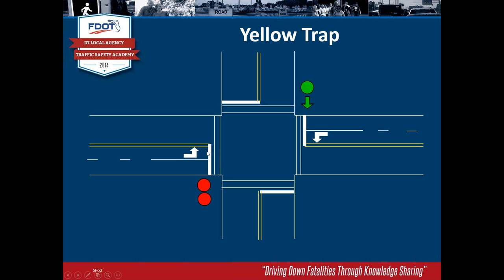Well, it's because he thought, as it went from circular green to circular yellow to circular red, that he could just go, that's the end of the phase, let me go through here. But this guy saw green while he was having a circular green. He saw green while the guy was in yellow and saw green while the guy is now in red. And so he just says, why did this moron just blow through right into the middle of my green? He must have run the red light. Well, he thought he was clearing. And this is what the yellow trap is all about.